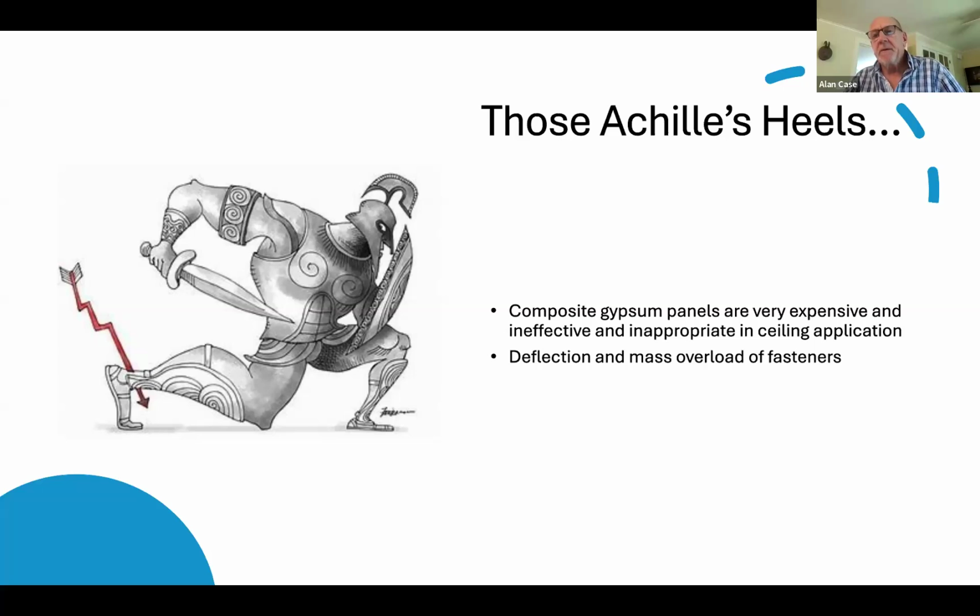And when the screws go through, there are like little loudspeakers for every screw attachment, so it doesn't decouple. It's still providing a path of travel. And then when you do have a decoupled system, it offers absolutely nothing. So there's a real misunderstanding about cavity insulations.